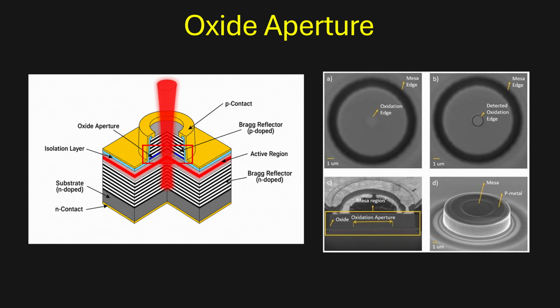The size of the oxide aperture is another important factor in VCSEL performance. This is a semiconductor layer containing aluminum that will be oxidized inwards, leaving an unoxidized opening in the center. The oxidized portion is insulative, so the current passes through the small opening, and the optical properties of the oxide layer guide the light into the smaller aperture as well.